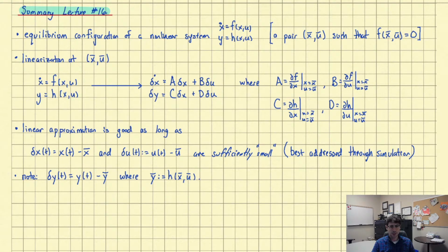And the first strategy we were talking about last class was this notion of linearization, right? So we're going to approximate a nonlinear model using a linear model. And we're using state space models to do this because, one, nonlinear systems are easy to express in this standard form, in this nonlinear state space model form. And the second thing is it gives us a nice systematic procedure for doing this approximation, for doing the linearization. And so we went through that procedure last time, and let's remind ourselves what it's all about.